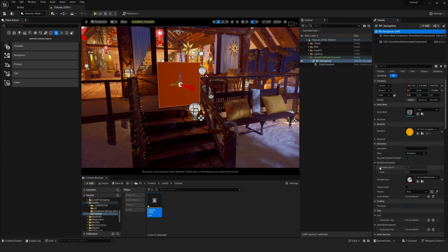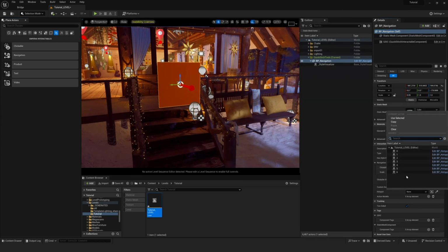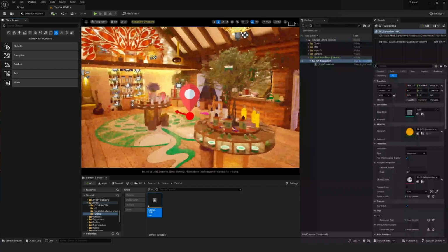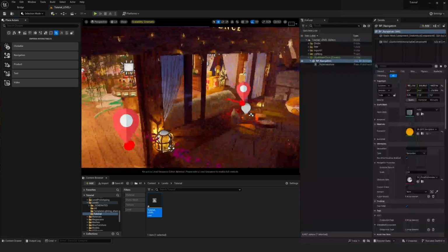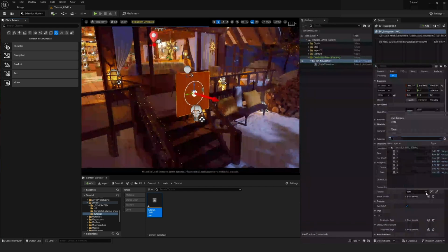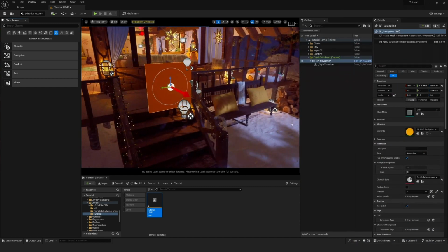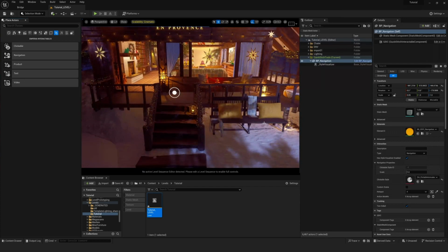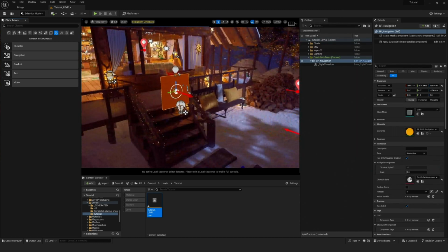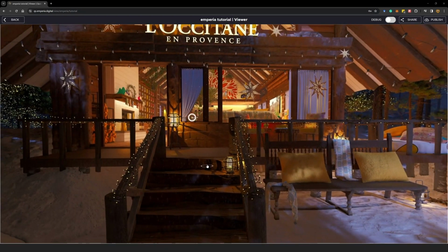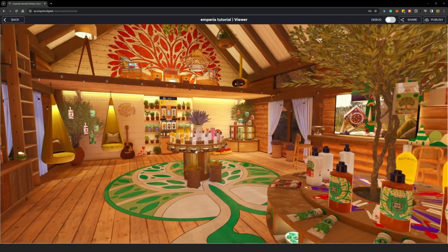And on the navigation blueprint, we can select a hotspot, and this hotspot is going to be the one that when you click the button, it takes you to. So if we selected this hotspot inside, which is 4, and if we go back to our blueprint and click hotspot 4, so in the tour now, when the user clicks on this button, they will be teleported inside to that hotspot number 4. Let's just see a little demo of that now. So as you can see, we click the button and we're now teleported inside.